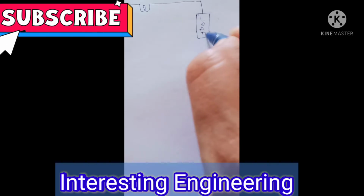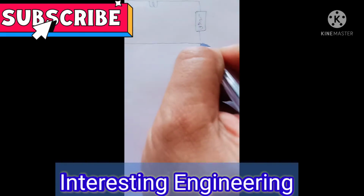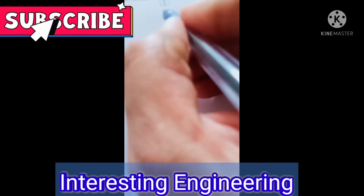Here this is the load and the current transformer's primary winding is connected over here, and to this primary winding we are connecting a secondary winding, and in the secondary winding we connect the meter that is meant for measuring the current value. Here this current is denoted by IP and this is the primary winding.